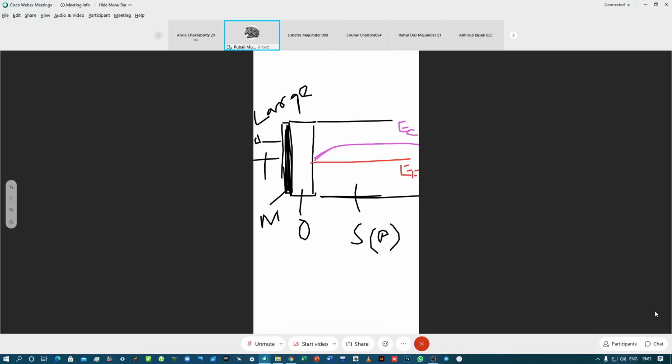Similarly, the valence band would move very much away from the extrinsic Fermi energy level, and the intrinsic Fermi level would also bend in such a manner that now you see that at the interface, the intrinsic, this dotted black line that I'm drawing, this is EFI, or the intrinsic Fermi energy level.